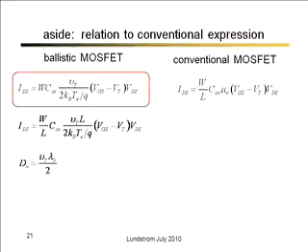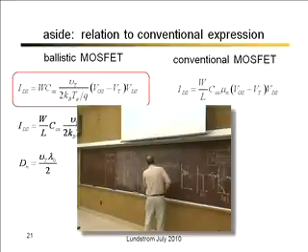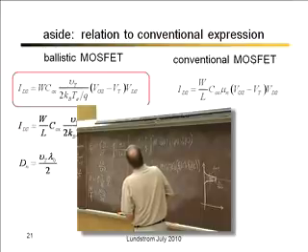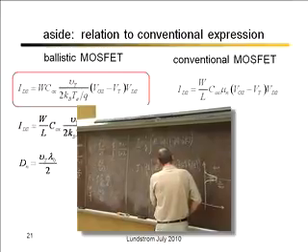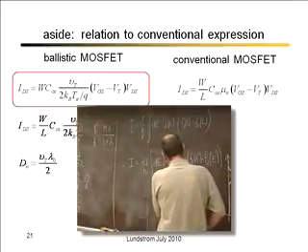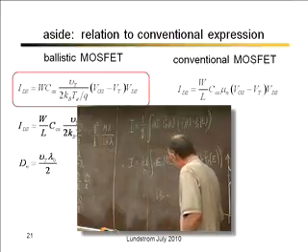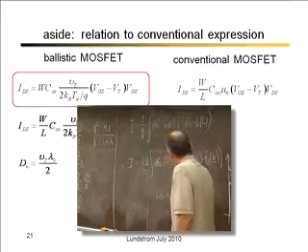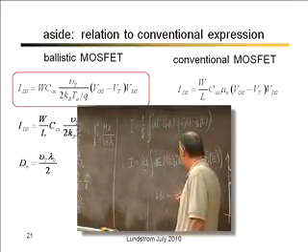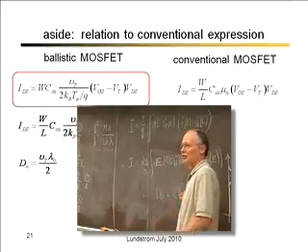One of the things I want to bring up is related to some of the things that Professor Dada discussed. He talked about how the diffusion coefficient, D sub n, and I think the way Professor Dada wrote it was the average velocity squared in the transport direction times tau. Now, you could write that in a little different way. I could take one of these velocities and multiply it by tau, and that velocity times tau would be the average distance between scattering events. That would be a mean free path.